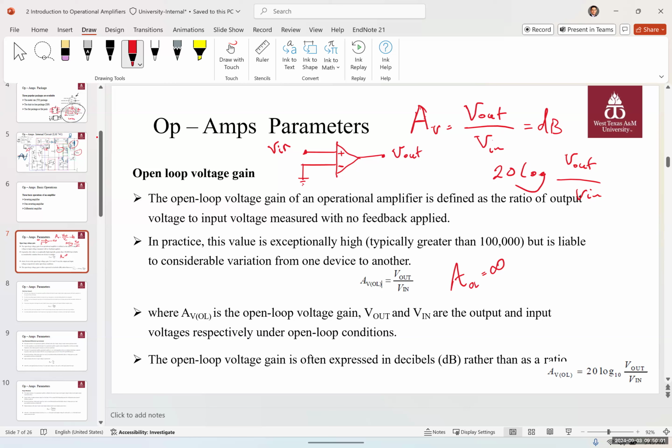In some op amps, we have 10 transistors, 4 stages of amplifier, and the gain would be 1,000. And in another op amp, you would have 50 transistors, 10 different stages of gain or amplification, and the gain would be up to 1 million. That's a pretty big number. Usually we don't like very high gains because it makes the system unstable. If I give it a gain of 100,000, it means if I give it 1 volt input, in theory, the output should be 100,000 volts or 100 kilovolts, which is impossible for an op amp to handle.